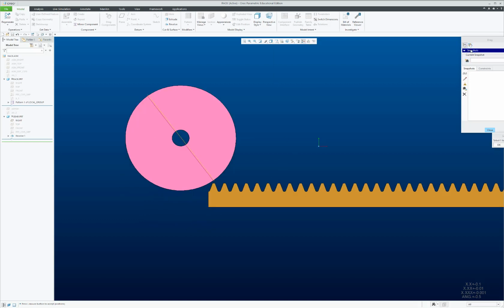Take a snapshot based on a constraint, let's say angle of motion of the pin joint going to minus 35 degrees, and take a snapshot here, minus 35, and we will engage it in motion all the way to 35 degrees when the tooth comes out of engagement.